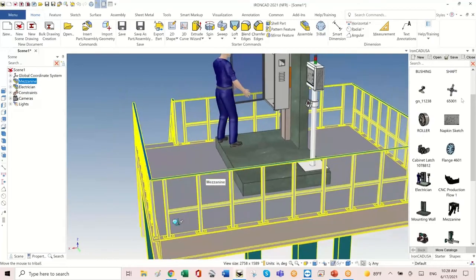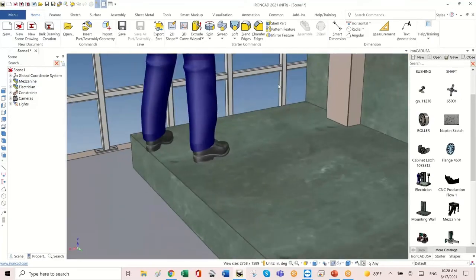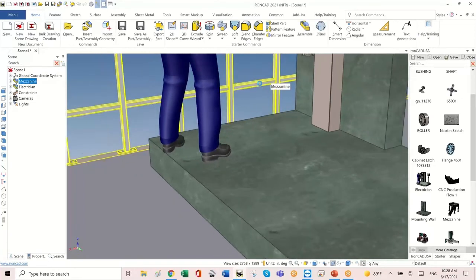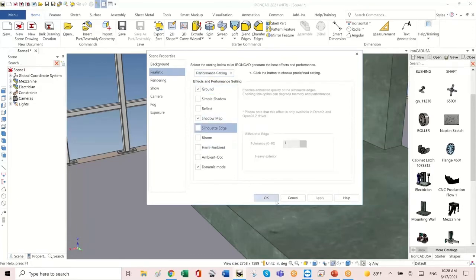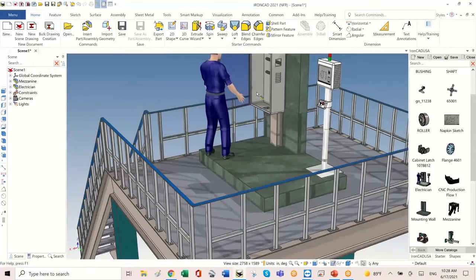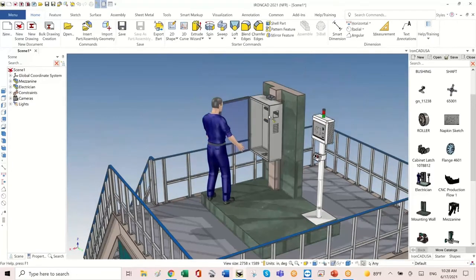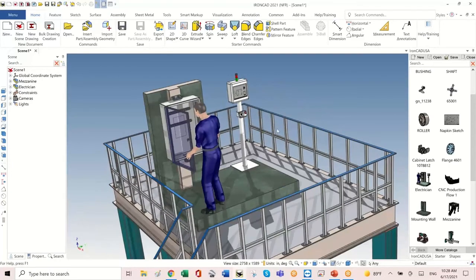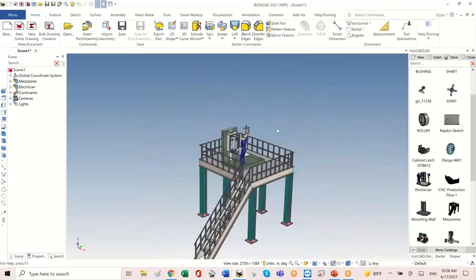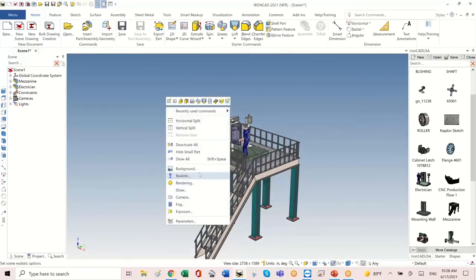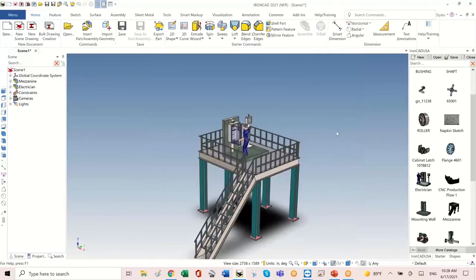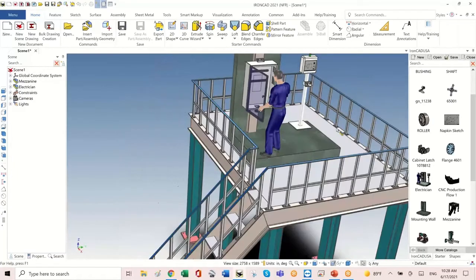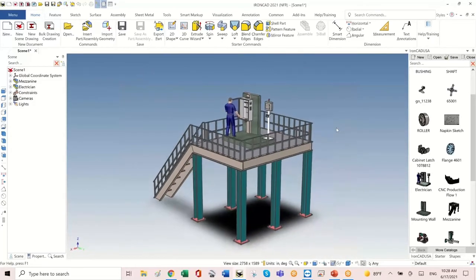So I've got this sitting, but now the load that's required to do this type of shadow mapping is going to be extremely heavy. And I'm just pointing this out to folks. If you're doing photorealistic rendering, it's great. If you're not, this can slow you down substantially as you work. So my simple advice would be only use these if you're working with rendering. Other than that, simple shadows work just fine. So you can see where the base of something is, and you can understand how things work that way.